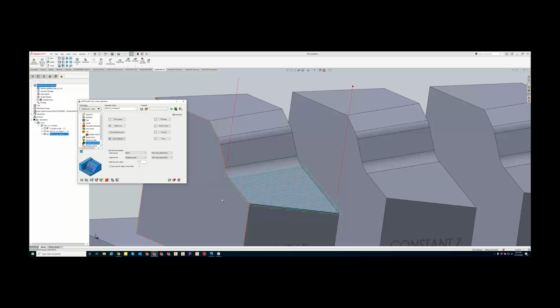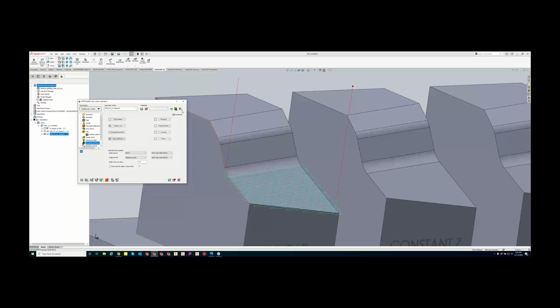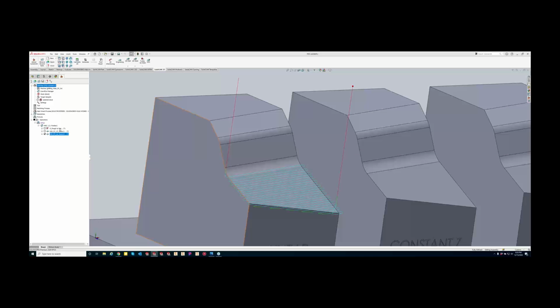You can see we're back to our same tool path because there is no stock. Well, there's stock there, but there's not more than 100 thou worth of stock. So that feature does come in handy, and I don't see a lot of people using that, but that option is there for you guys. Hey, Kevin, can you adjust your 3D iMachining roughing pass just to leave, let's say, 1/8 of an inch on those surfaces? Absolutely.